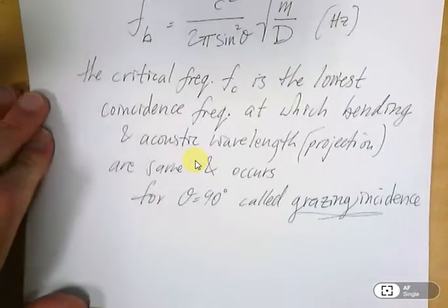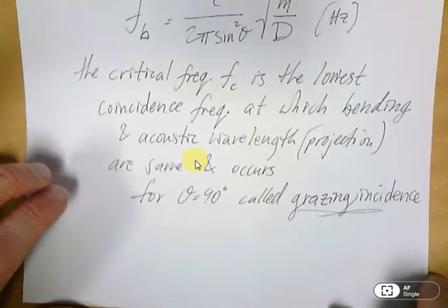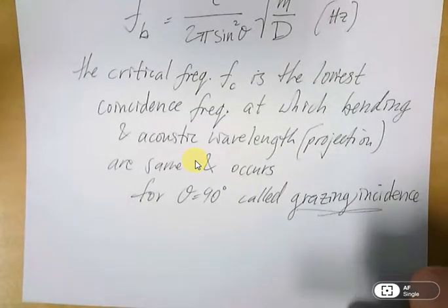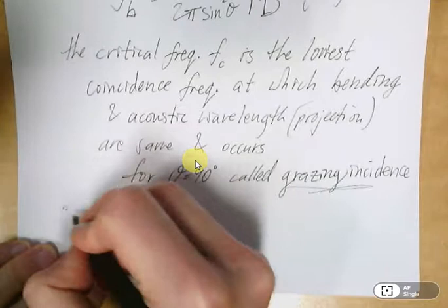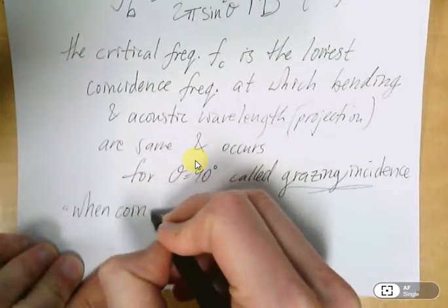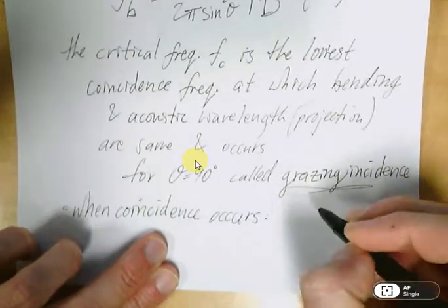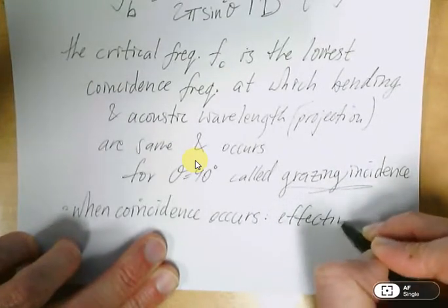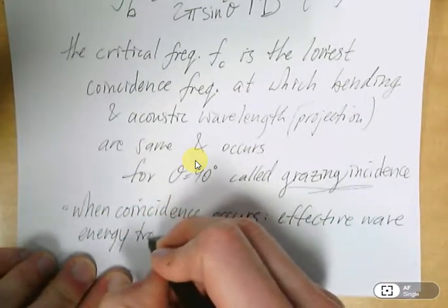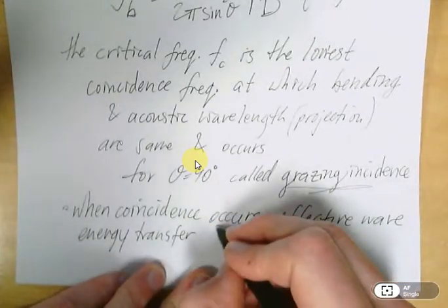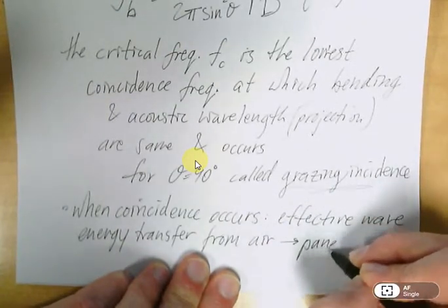Like the case of the critical frequency itself, when coincidence occurs, there is an effective wave energy transfer from air to the panel, and if it's bounded by air on the other side, then from the panel to that other air.